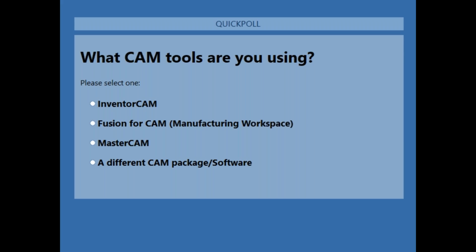As far as CAM tools, we've got the integrated CAM solutions within Inventor. Fusion has a couple of different caveats to it, depending on how complex your operation sets are. Fusion allows for some standard 2.5 axis and some turning operations embedded into Fusion, but you can also pay for the manufacturing extension, which gives you much more complicated tool sets for 3+2 and complex manipulations of the 5th axis and so on.